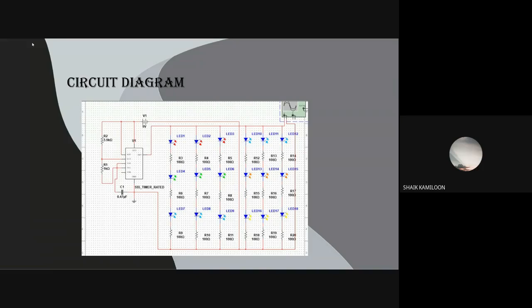The timer which we have used here is a 555 timer. The basic timer gets its name from the fact that there are three internally connected 5 kilo ohm resistors which it uses to generate the two comparators' reference voltages. It is a very cheap, popular and useful precision timing device which can act either as a simple timer to generate single pulses or long time delays, or as a relaxation oscillator producing a string of stabilized waveforms of varying duty cycles from 50% to 100%.